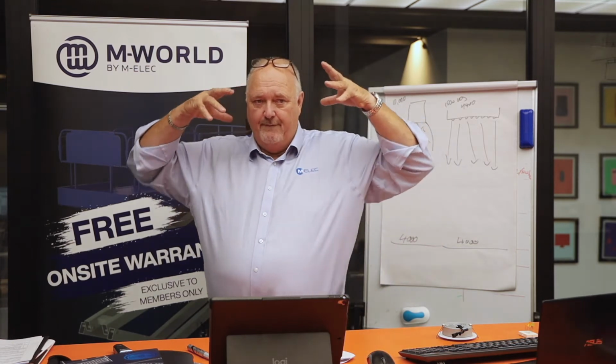But when we're in here, what we're looking for is a good average lumens per watt. So somewhere in the 80 to 100 in here, in our lab, or outside, 100 plus. Or if I had a retail outlet, or a motor dealership and I was trying to light up motor vehicles, I would be looking for that 100 plus lumens per watt, because I really want to emphasize and show the colors and things like that. So I want it as bright as possible.